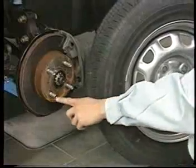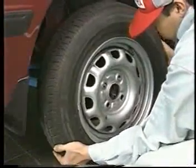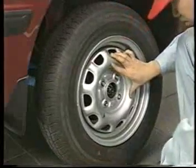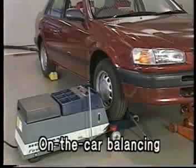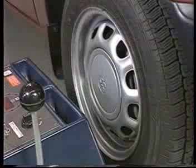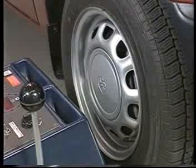When wheel balance is attained, fit the tire back on the vehicle in accordance with the register mark you made earlier. Check again that the tire does not have runout. Then check the on-car balance. The on-car balance is checked with the wheel cap, valve cap, and center ornament attached.